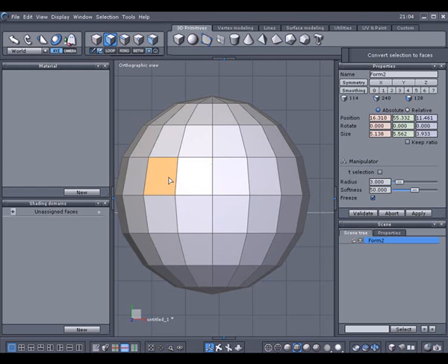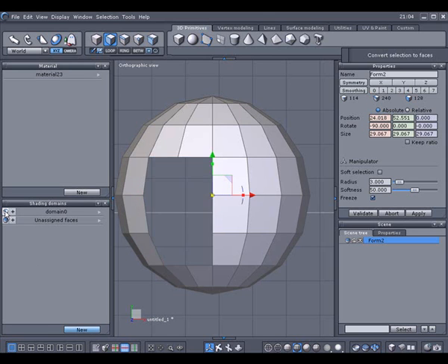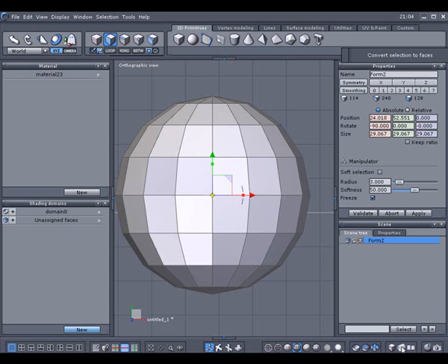What I'm going to do is I'm going to select a few faces here, then I'm going to select new, and then let's set up a new shading domain so I can hide or show this. As you can see the back side over there is because I need to set my show hidden faces back on.